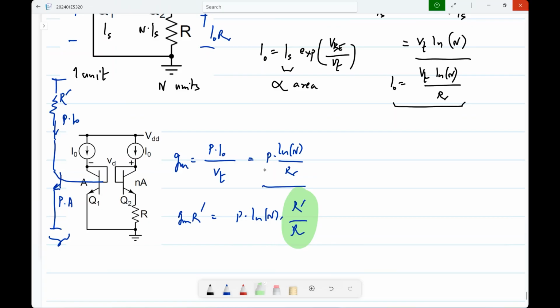It may be less than with voltage biasing. In the case of a bipolar transistor, the GM would have been inversely proportional to absolute temperature. But what is the current here? This current itself is proportional to absolute temperature. So by having such a current which increases with temperature, you eliminate the variation of GM with temperature.